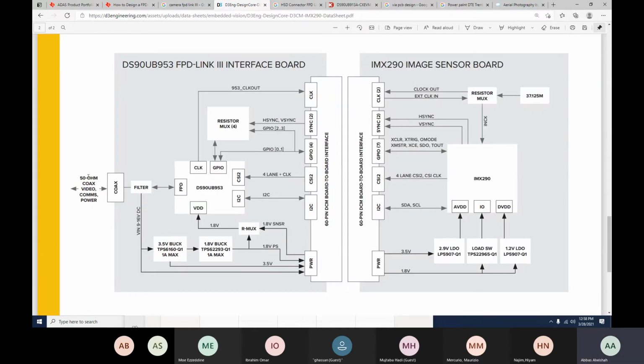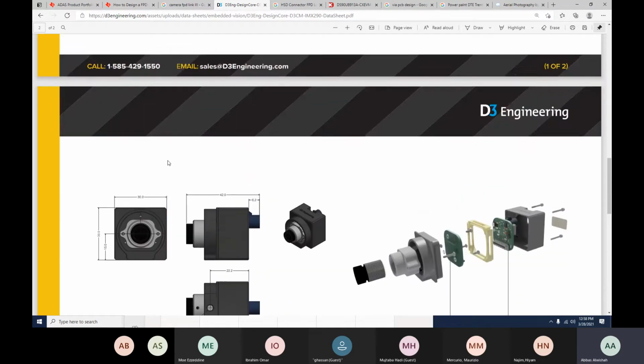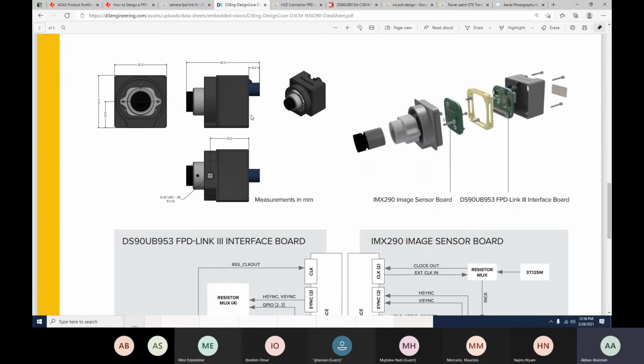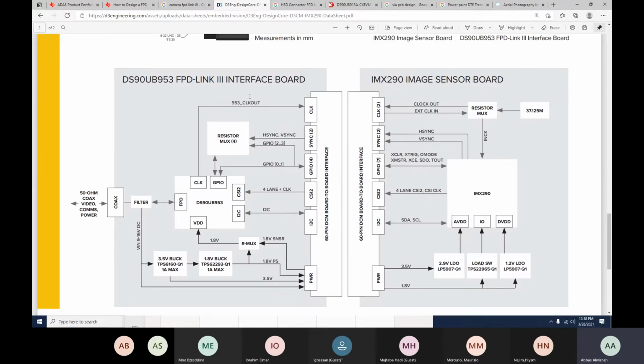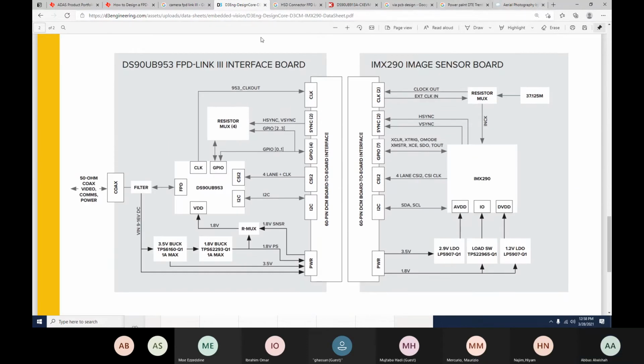So the coax connection is also providing the power too. You don't want to have two connectors, one for power, one for data. If you were running this over Ethernet, what they call PoDL, power over data line, this is coax, this is power over coax. So within one system, you have the coaxial connection, you have the power on the shield, and then you have the data on the center contact.